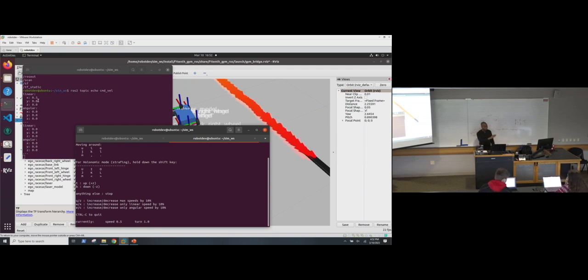So it's giving the force in the X direction, and that's what's making the robot go in the X direction. And then I made it stop. I hit the K button, and it just put a 0 onto that frame, and that's why it stops. So with the command velocity, when we're publishing a topic, I can make a robot move by just giving it velocity commands, and I can navigate that way too.